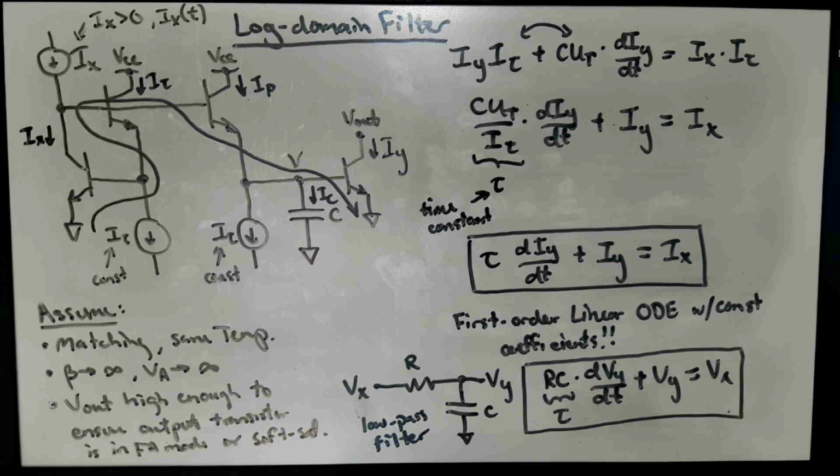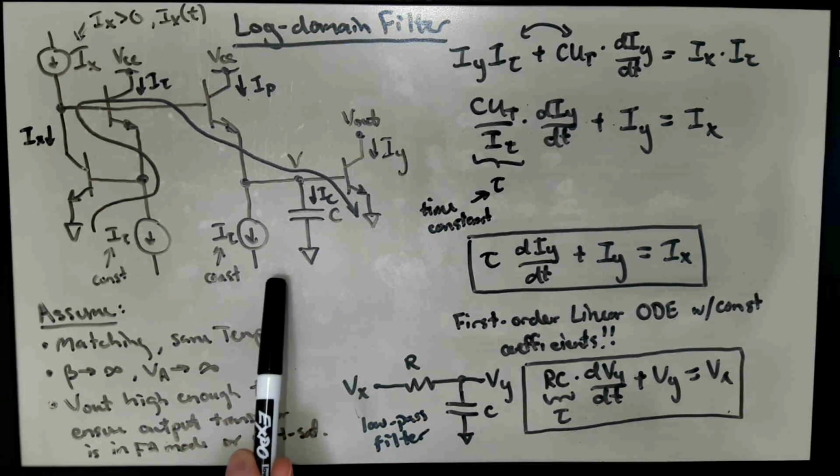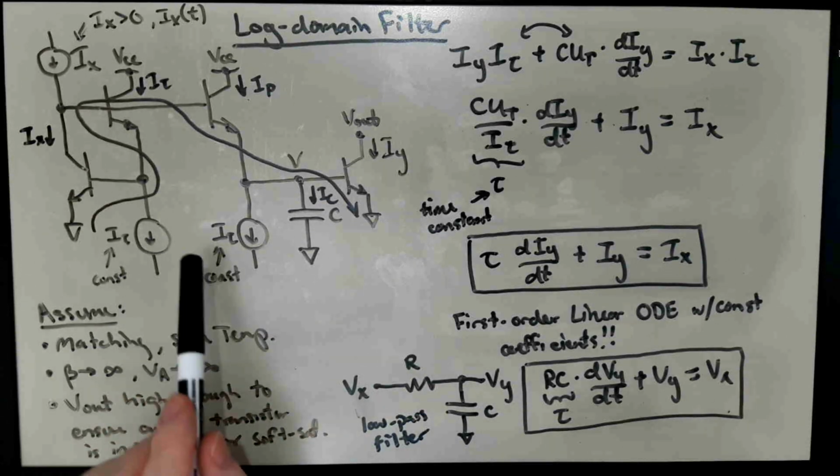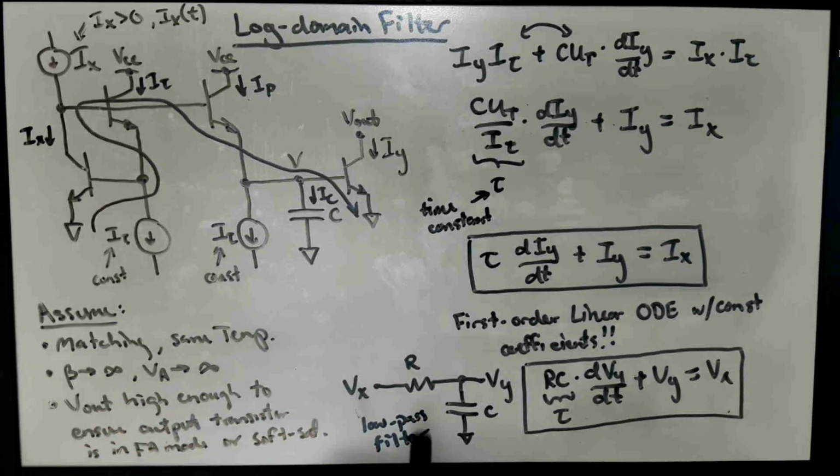And to get anything other than maybe a few hundred ohms or so takes an enormous amount of area. And so while this may seem like it's a very easy thing to do with discrete components, it turns out something like this is much easier to do on an integrated circuit. So that's one thing to note. It's just that you can spend 1,000 transistors to do the work of a single resistor if you want to without any difficulty.